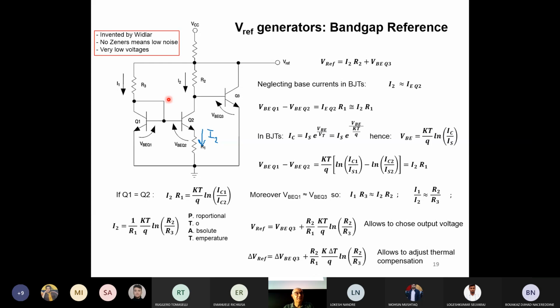You know that if you cool down a semiconductor, you will not have the thermal generation of charges inside. You will not have also the ionization of the doping. So usually this circuit gives a voltage proportional to the absolute temperature, but usually starting from minus 50 degrees up to 125, 150 degrees.